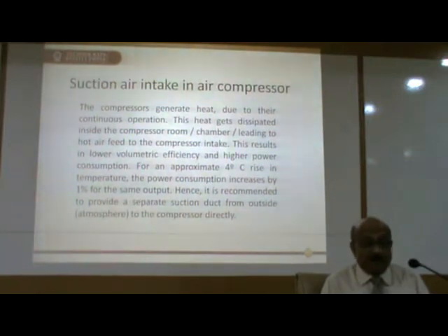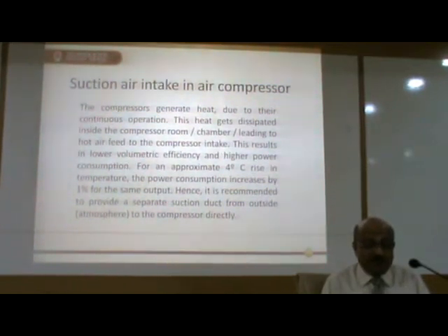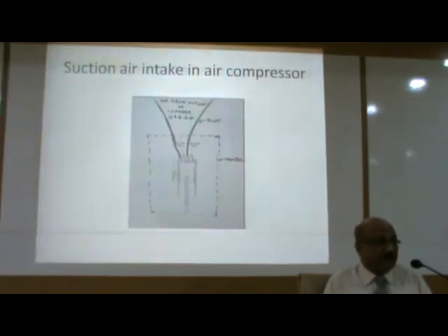For an approximately 4 degrees centigrade rise in temperature, the power consumption increases by 1% for the same output. Hence, it is recommended to provide a separate suction duct from outside directly to the compressor. In the next slide, I am showing the diagram.